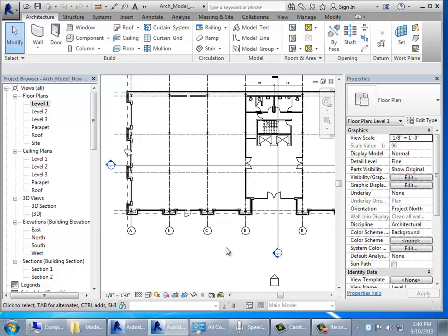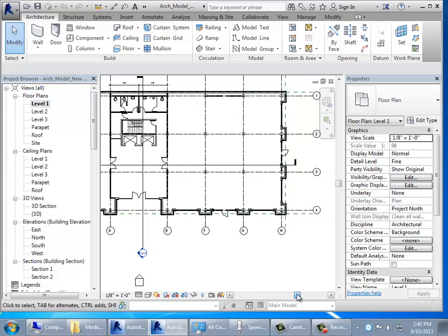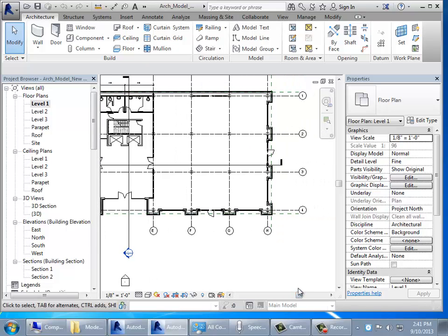They have the grids as their landmarks, and then they share those files, and the architectural modeler starts doing architectural components, and the structural modeler starts doing structural, so that they have those reference lines to get those two pieces together, right? You don't want your building's lower left to correspond with the upper left. You want them to overlap, and those are their grid lines, basically. Yeah, reference lines. Your most important reference, get those right.